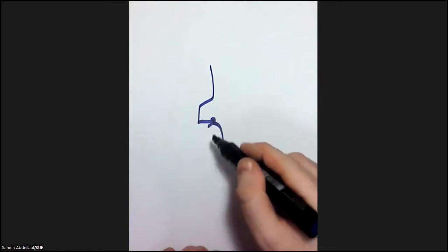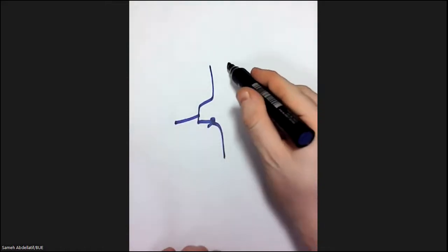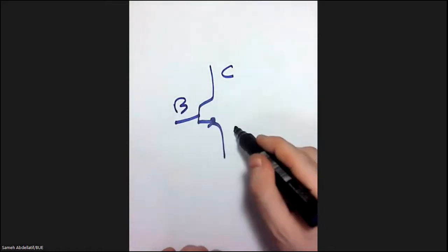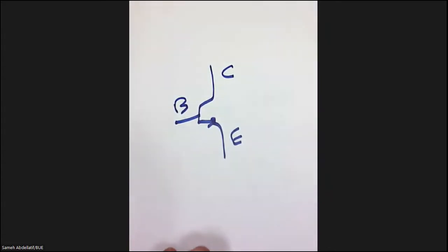Now, you would like to make a diode. So in order to integrate a diode in a CMOS technology, you have to integrate it in the form of a transistor. How can we do so? Let's turn back to the basics of a BJT. A BJT with a collector, base, and emitter is simply either an NPN or a PNP junction.